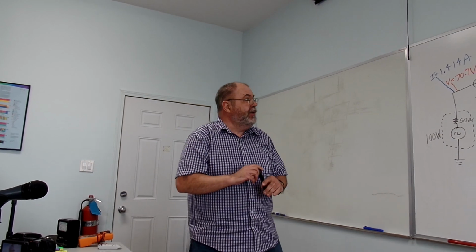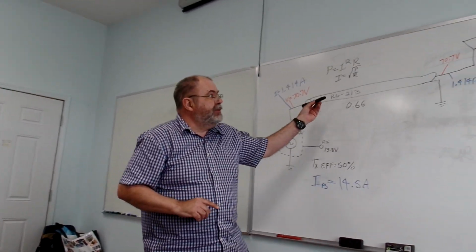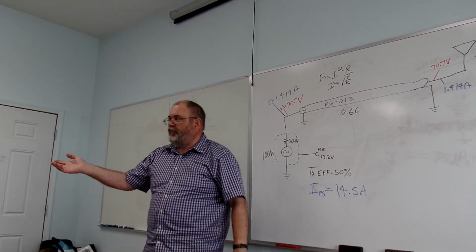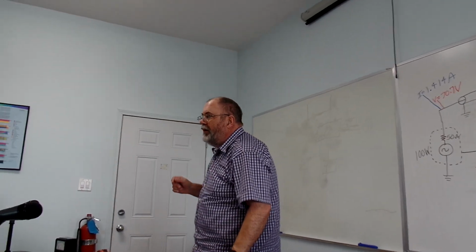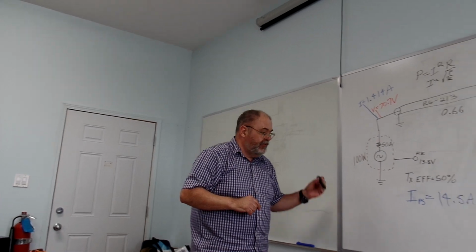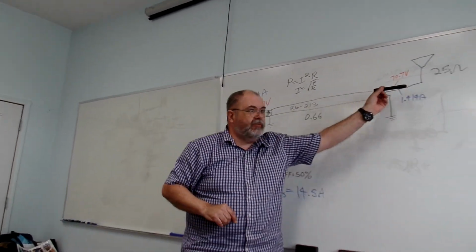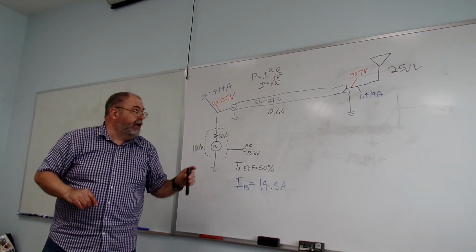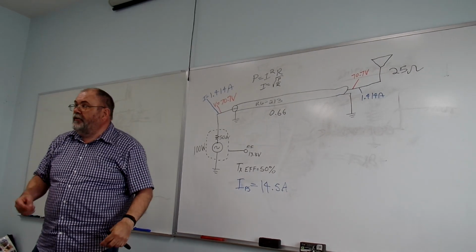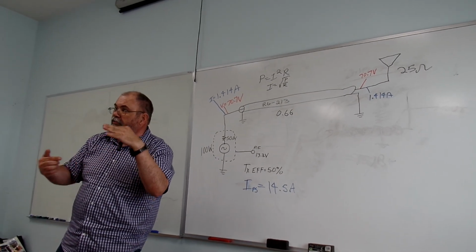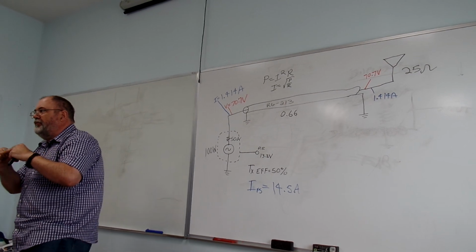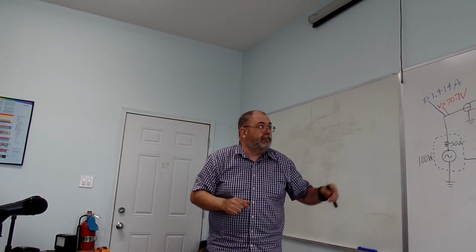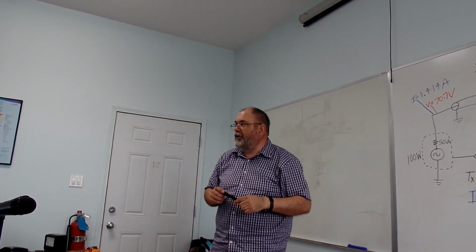Okay. So this thing of the wave coming down here, reflecting and coming back happens faster than we can blink our eyes. It happens very, very quickly. And so what happens is you get a constant stream of waves coming that way and a constant stream of waves reflecting back. And along the feed line, the waves will add when they meet, crest to crest, and they'll subtract when they meet crest to valley, and you'll end up with what they call a standing wave pattern, or an SWR.